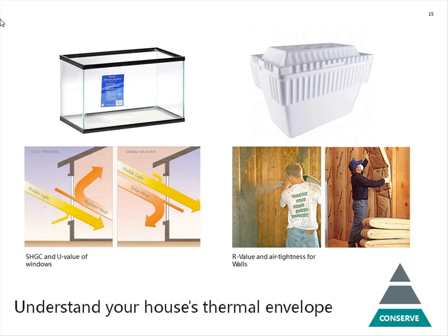For glass, we tend to think of it as nothing, but it's actually a very sophisticated material. We want to be able to allow in light, but typically block heat. And since they both exist along the electromagnetic spectrum, it's a very difficult thing to do. We have something called a solar heat gain coefficient, SHGC. It's a very important way to judge the performance of your window.